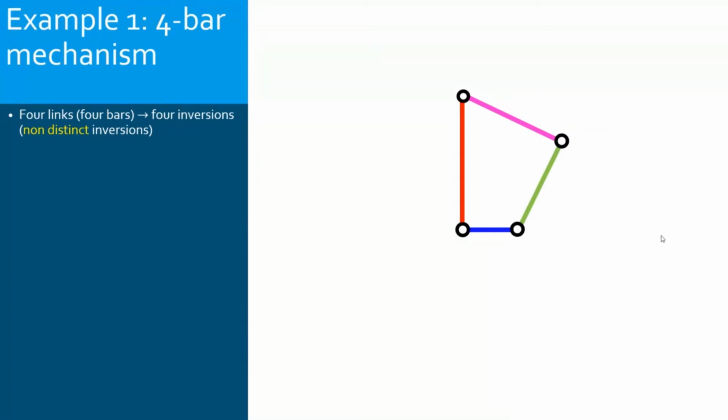Of the 3 others, 2 bars are connected directly to the ground and have fixed axis rotation, and 1 bar will have a general motion. So substantially, I have no difference, because I will always have 1 ground and 3 bars moving, and of the 3 moving bars, 2 have fixed axis rotation and 1 has general motion.